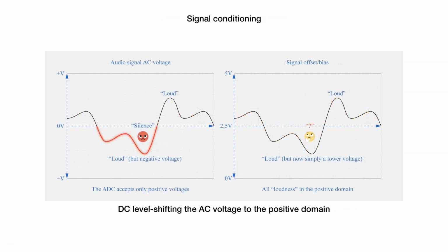By default, the audio signal fluctuates around 0 volts. This is why the signal must be conditioned electronically and then in code. At the standard 5 volts, the silence level of 0 volts is offset to 2.5 volts by the microphone amplifier circuitry. However, all the positive and negative peaks, that means all the loud parts, are now above 0 volts. And how do we know where the silent zero crossings are?